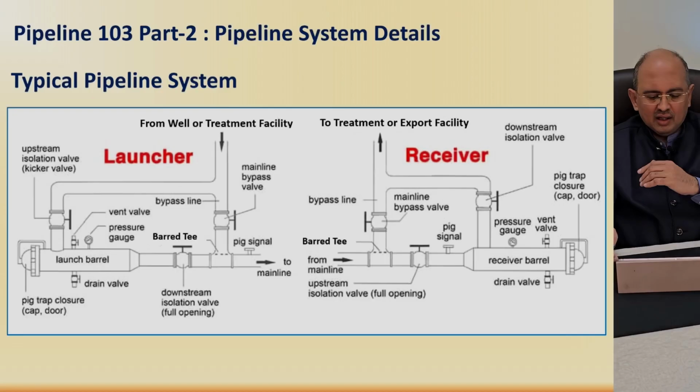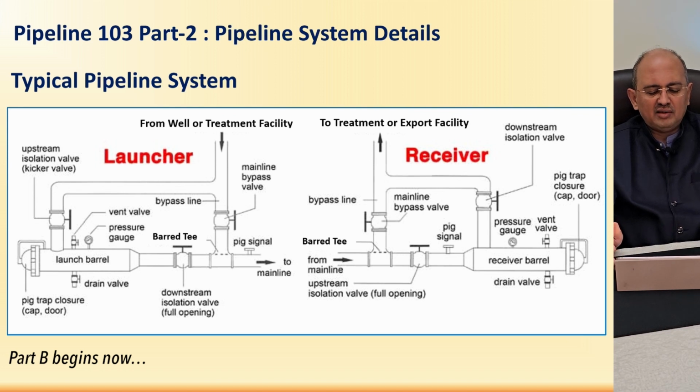to take place. So this is the typical pipeline system, and to be able to perform all such activities, we need all these elements to be designed and installed in the pipeline. Design means, like we have seen for the pipe, the thickness calculation based on the hoop stress and the longitudinal stress.